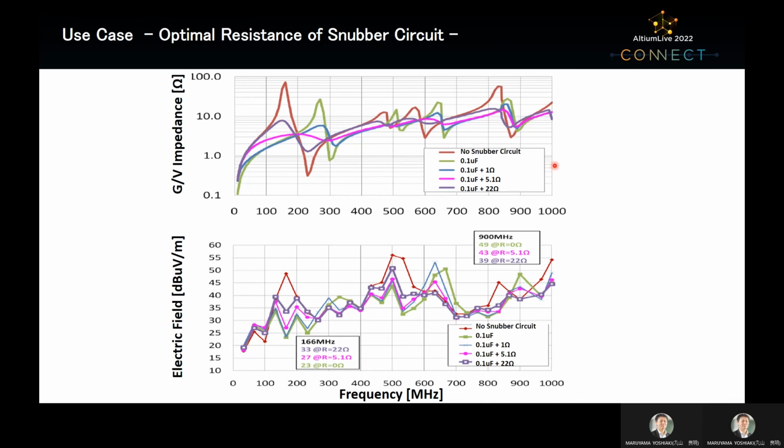In the actual design, it is necessary to perform simulation in advance to control the resonance between power and ground at the layout design stage.